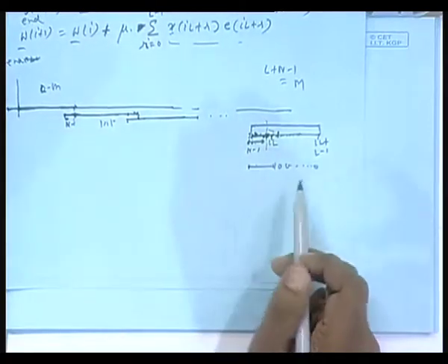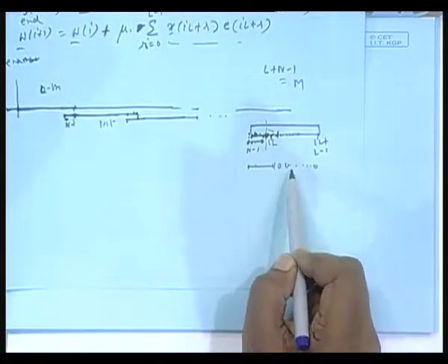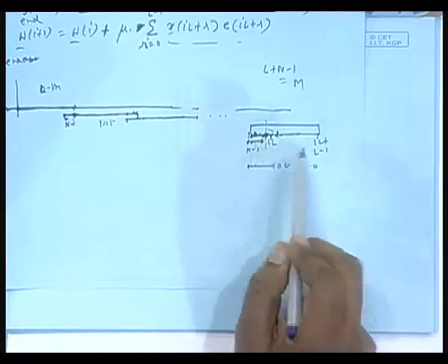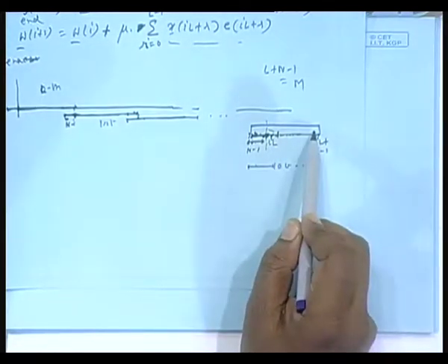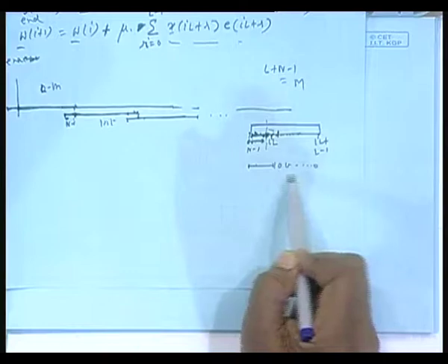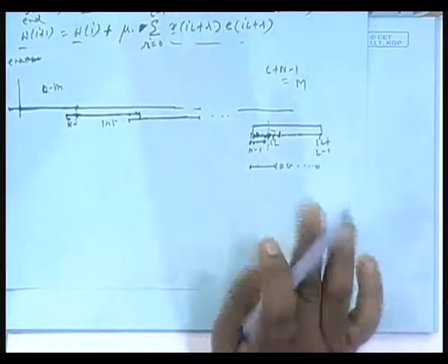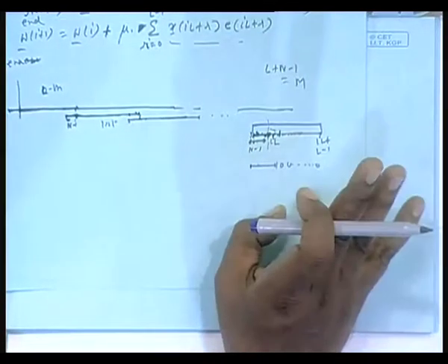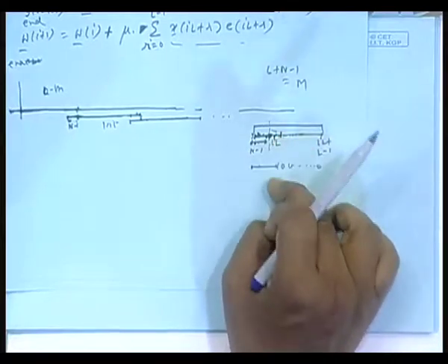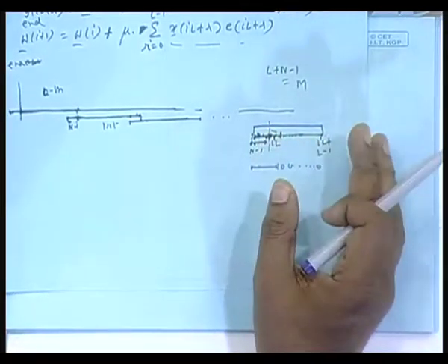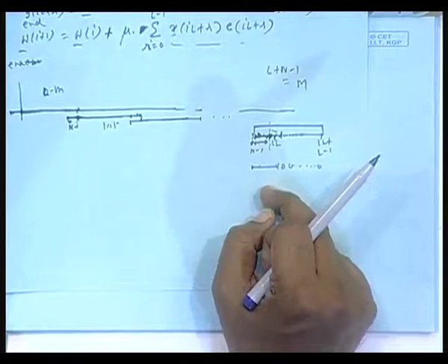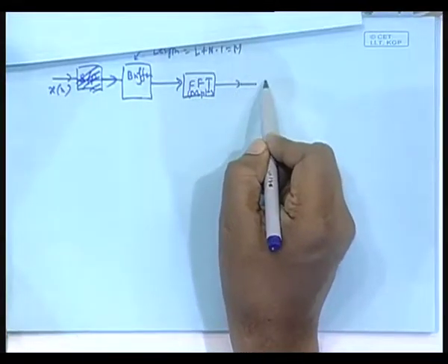So, that means what I have to do? This FFT I have found out. If I know this FFT, suppose by hook or crook I know this vector and its FFT is known somewhere, then the two DFTs will be multiplied and I have to take inverse DFT, ignore the first n minus 1 sample. That is the filtering part. So, suppose I do this way.